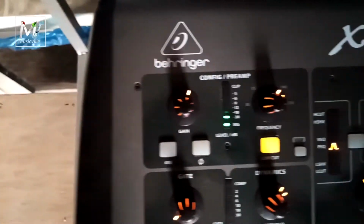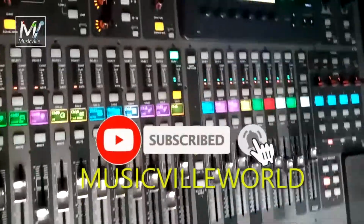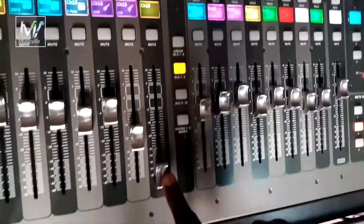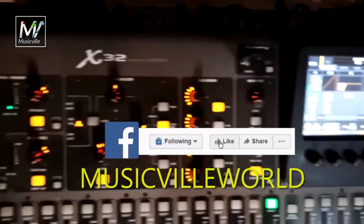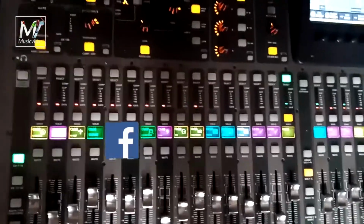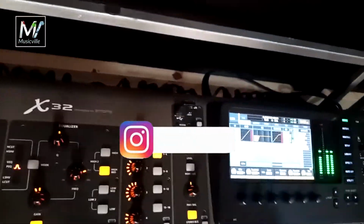Then it comes into your preamp. Your preamp feeds the equalizer, down to the compressors, to the gate, and up to this point, then to the mains. Your gain is independent of this volume. This is not your actual energy sending in, but your gain determines the energy that comes into your mains. We have to be very, very careful about that. We have to be very careful about what we do with the input gain.